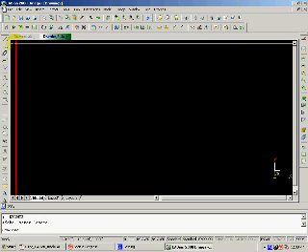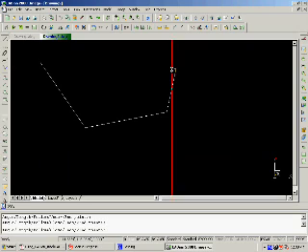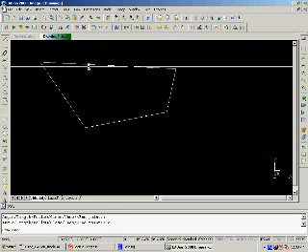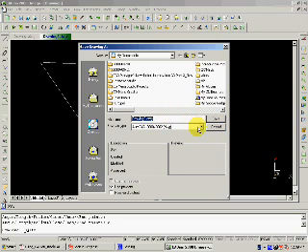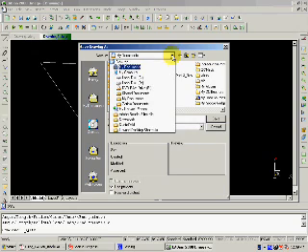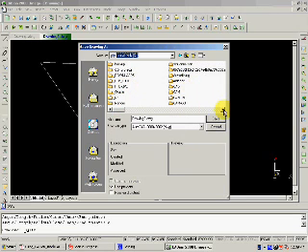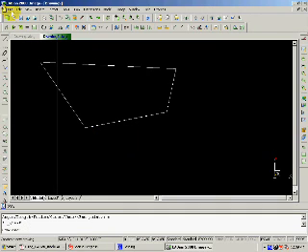Okay, what else do you have? Drawing a line. Very simple. You can draw a line, and at this point, I'm typing C. You'll see at the bottom, it'll close that polygon I'm doing. The other process you can do is we're going to save this drawing now, and you've got a choice, save as or drawing a format, whatever you want, DXF, variety of choices here, and a directory wherever you can go to find your file, folder, directory, whatever you want to save this thing to. I'm going to cancel at this point.